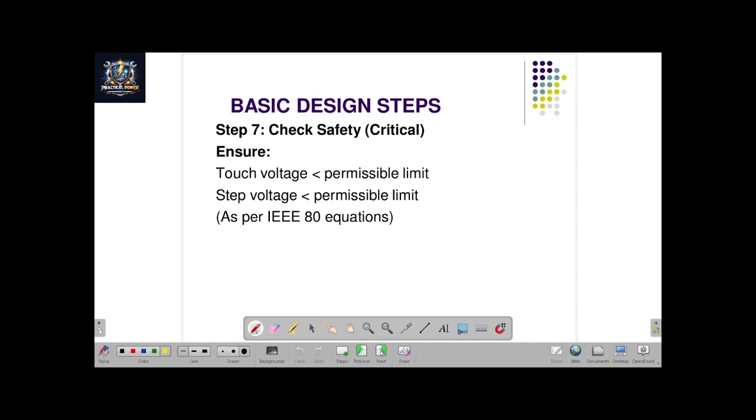In step 7, check safety criterion. Touch voltage should be less than the permissible limit. Step voltage also less than the permissible limit as per IEEE 80 equations.